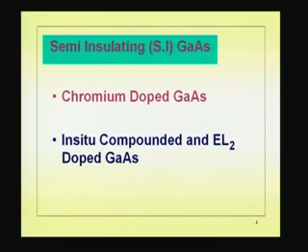In one way, if you take polycrystalline gallium arsenide and melt it and grow, it turns out to be n-type from the crucible and from the contaminants, otherwise it is p-type. So, if it is n-type, you use chromium for compensation. If it is p-type, you use that EL2. That EL2 is a particular name, with no expansion, it is called the EL2 center.